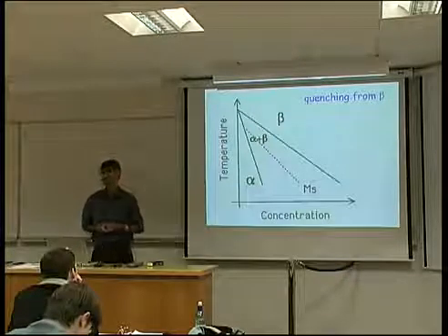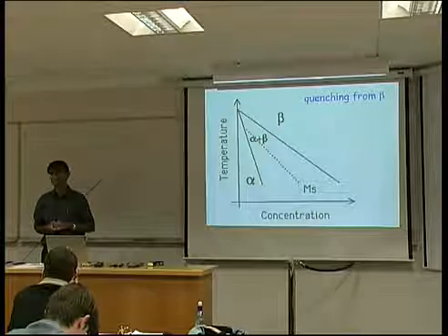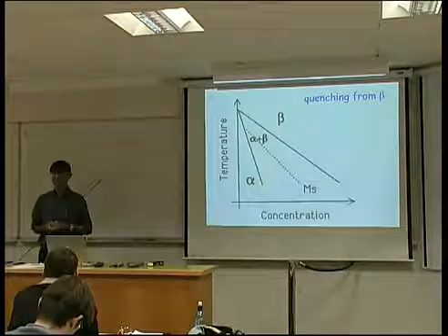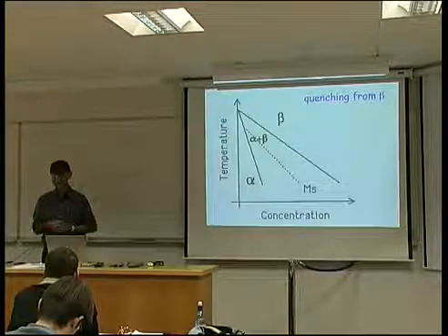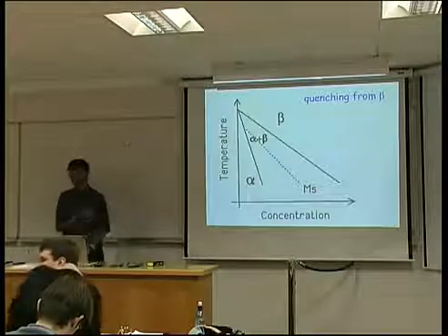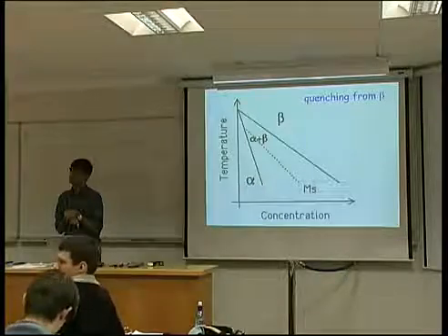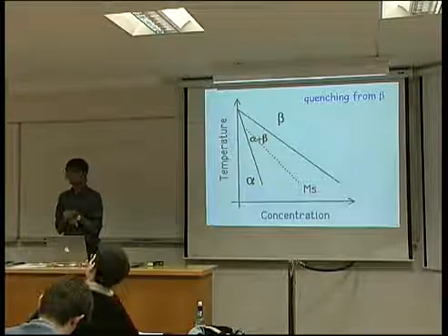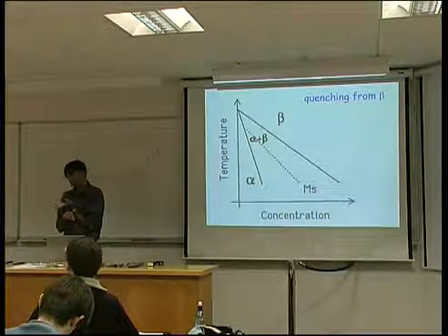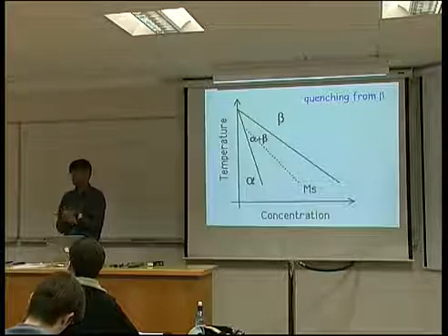Would it be possible to make the entire material change? Because then you surely can have a really good reversible. It's a good question. I don't know is the answer, but it's a very good question to think about. So does that, just sorry, again, I'm trying to imagine the idea of trying to fit that many atoms in. Does that initiate a large amount of stress in that single planes? It does, and this is the reason why we get a peculiar C upon A ratio, and also why we embrittle the material when the omega phase forms.